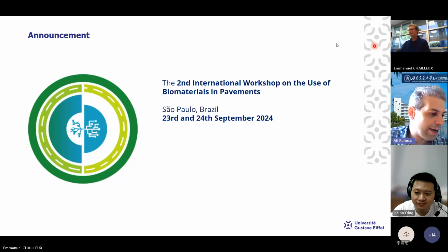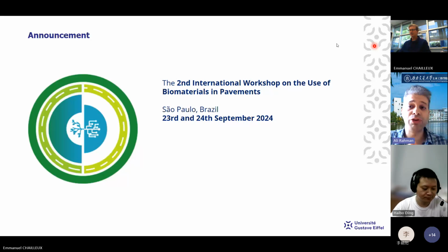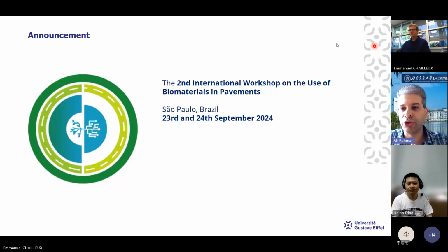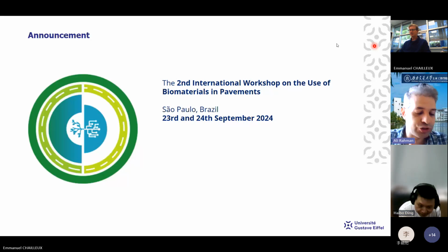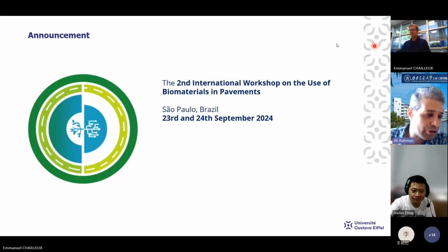Okay. So I also have another question about the delta method and the MIA index, which is very interesting, and how to connect the molecular structure of the asphalt binder with the linear viscoelastic behavior of the asphalt binder material. As you mentioned in your presentation, at the end in your conclusion, this is the connection for the next steps, which is going to the mixture level and the structure design of the material.